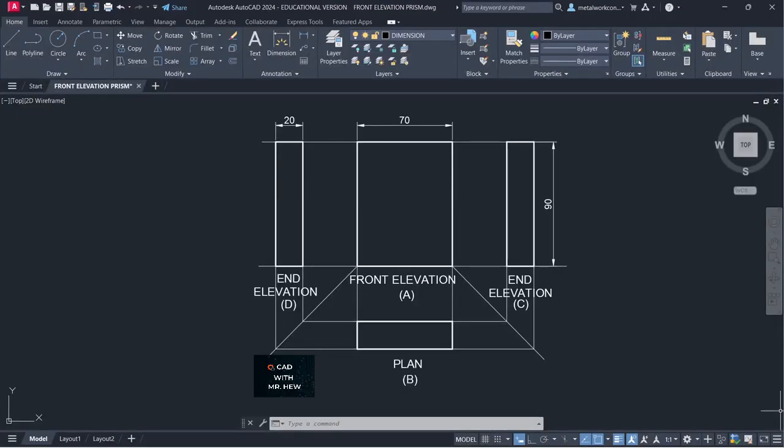On the screen is a first angle projection drawing of an object, and we will draw this object in isometric projection. So what we need to do, we need to identify where is the lowest point on the drawing.